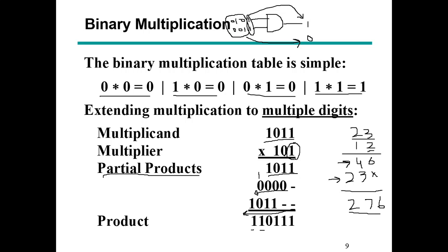And when you move from the least significant bit to the most significant bit of the multiplier, you shift the partial product by one bit position. So binary multiplication of multi-bit numbers is basically binary shifting and then adding. So these are two operations that are used to implement binary multipliers. Shift plus add, these are the two operations used to multiply two multi-bit numbers. This is the product.